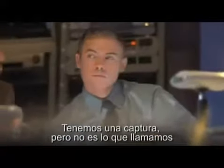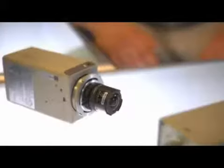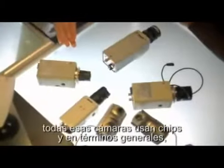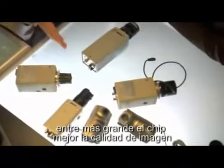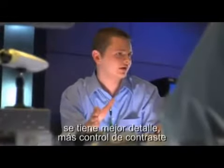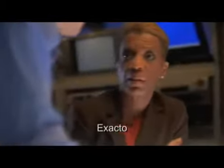There's just not enough detail. We've got a capture, but it's not what we call recognition quality. The resolution is too low. We got analog, digital, black and white, color. Now all these cameras use chips, and generally speaking, the bigger the chip, the better the picture quality. You get better detail, more control of contrast, like between very bright and very dim areas. Like in the pharmacy. Exactly.